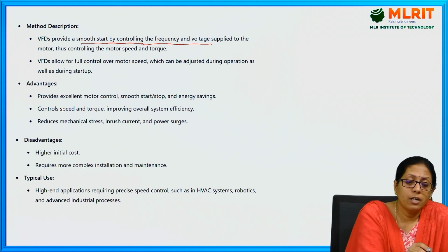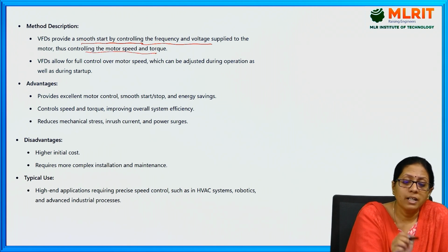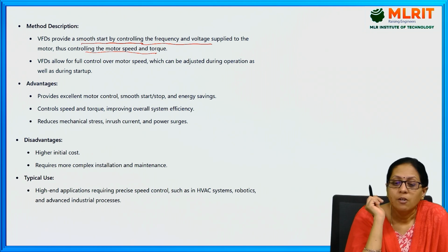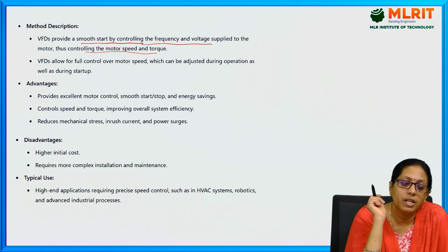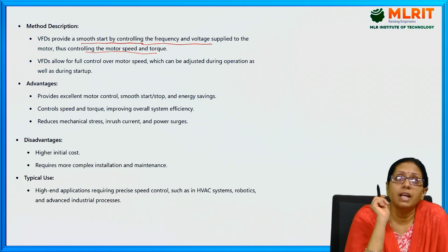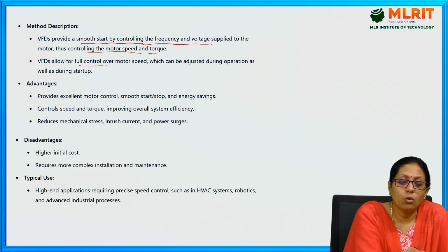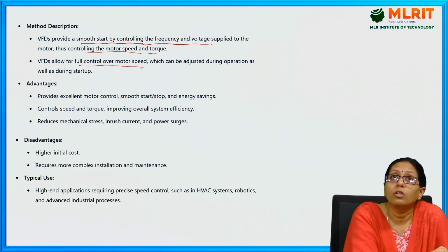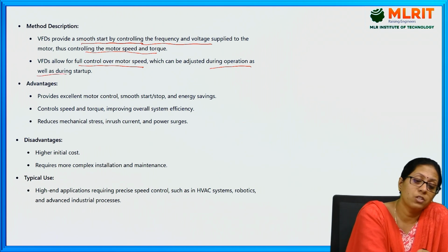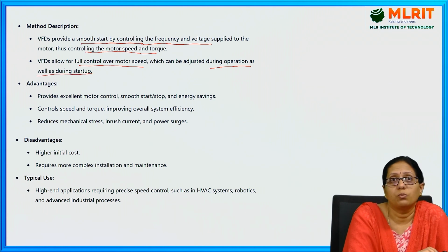And controlling the motor speed and torque. By using the frequency as well as voltage, we are controlling the motor speed and the torque. VFD allows full control over motor speed, which can be adjusted during the operation as well as during the startup also.